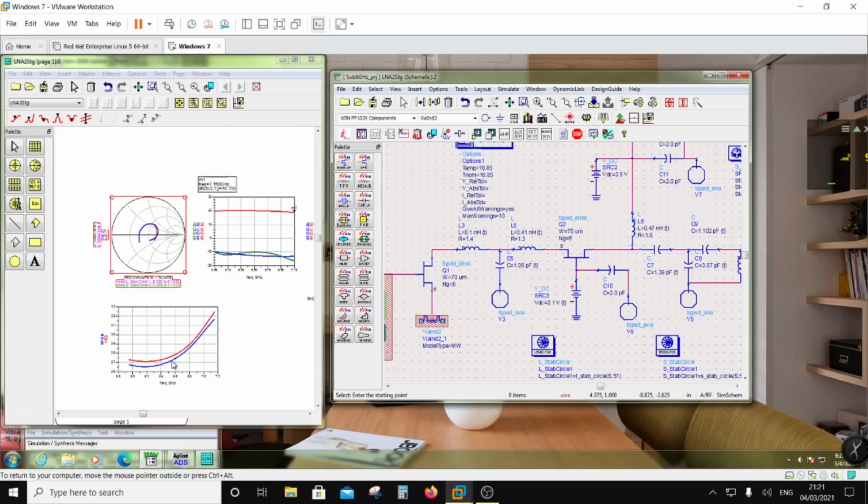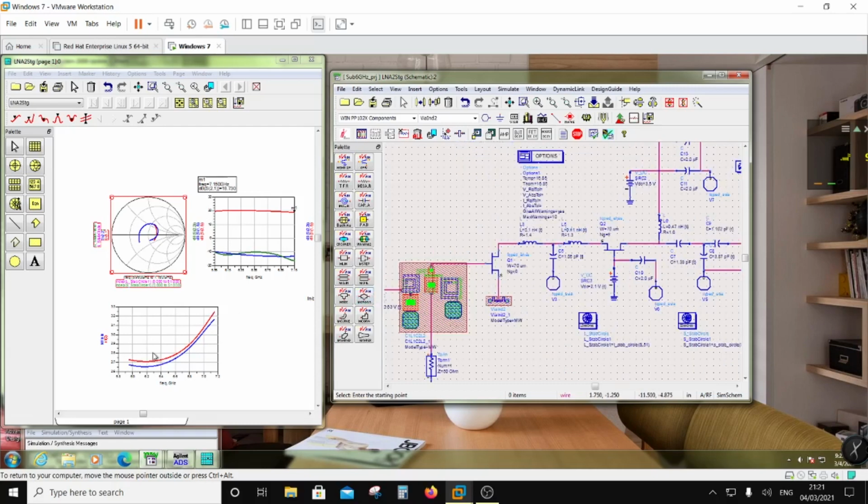And the thing you would notice here is that we were sitting at a noise figure of 1.85, and then suddenly it has shot up to 3.2 as a worst case, right? So now it seems like this noise figure and NF min have been differing a lot, right?